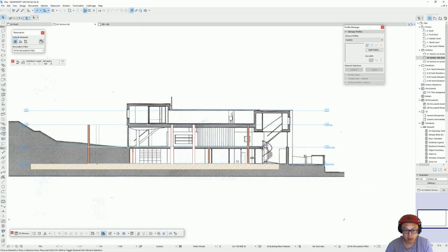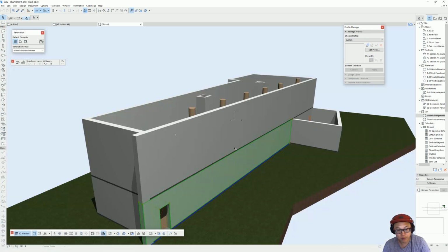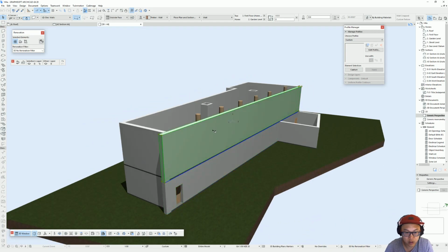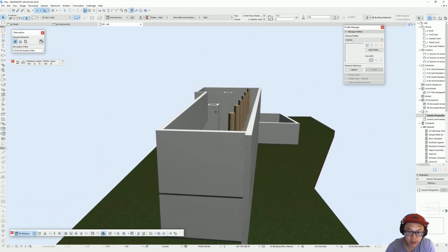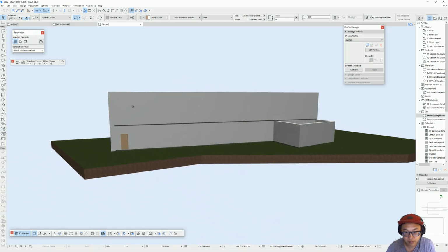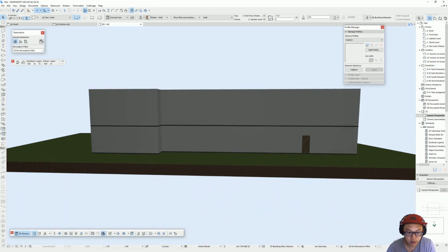Yep. And now if we go back, you can see I changed size because those walls are actually stuck to the bottom of the first floor level. So if I change the story level, the wall height, and all those elements that have a property that allow it to be stuck to a level, they will move. Okay, good.